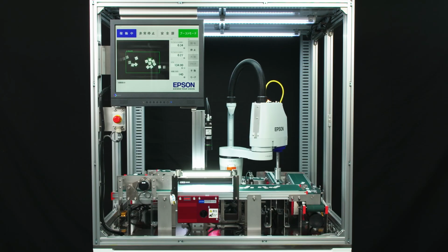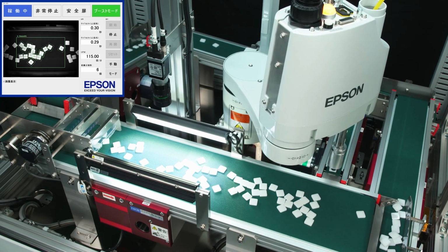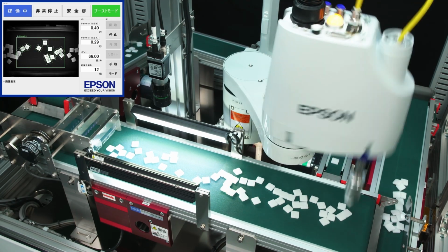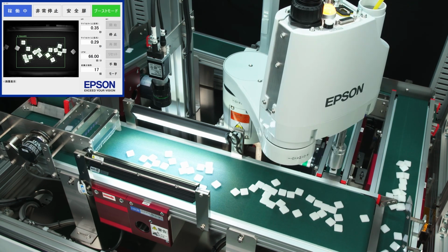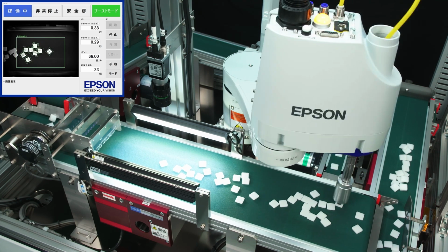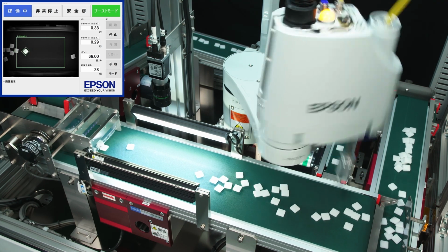Pendants or PCs are great for running a single work cell. Even if that work cell contains a bunch of different pieces of equipment like conveyor belts, vision, feeders, maybe even multiple robots, it can be run off a PC. Although you may need to run a third-party GUI if you add components from multiple vendors or if you add multiple robots into your work cell.